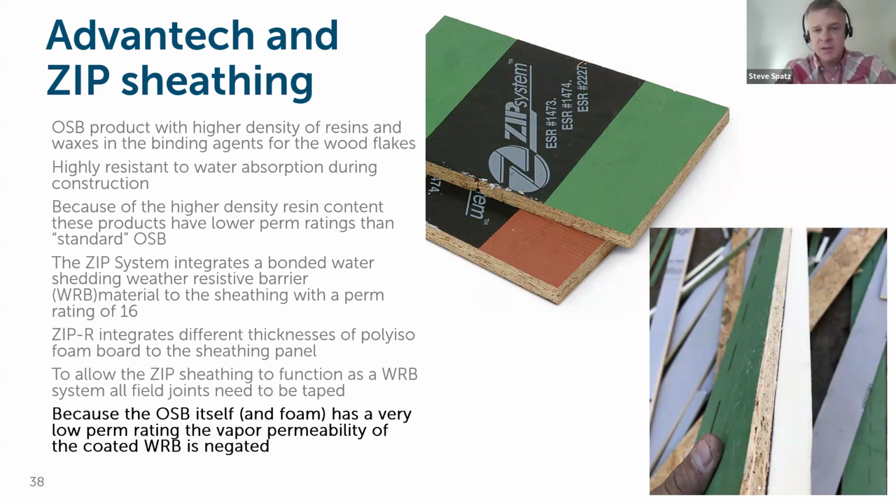So using the zip sheathing and/or the zip R product with the integrated continuous insulation layer, you have to be considerate of the fact that you're not going to get very good, if any, drying potential whatsoever to the exterior in that assembly. You're going to need to give a pathway for any moisture loading within those assemblies to be able to dry to the inside of the building.